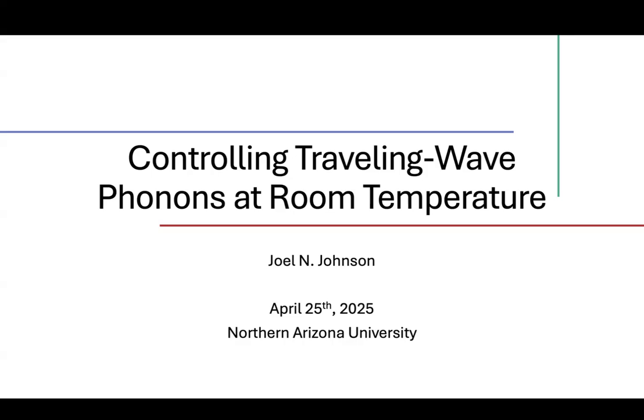Here I have a weight with side weights that are specially tuned, and it is allowed to move up and down on the spring. So if I inject this system with a little bit of rotational energy and let it unwind, we see that the weight begins to spin, and because of the tuning between the two coupled oscillations, energy begins to transfer to longitudinal motion of the spring.